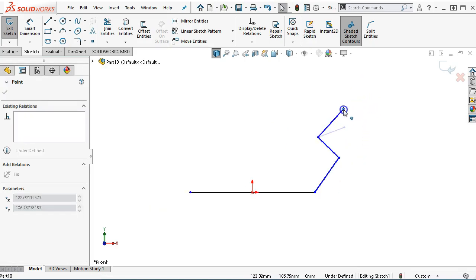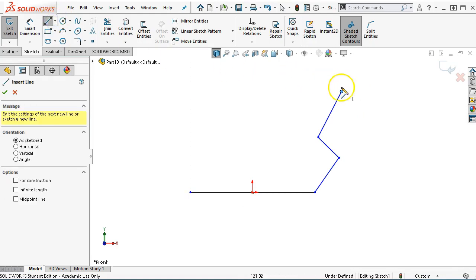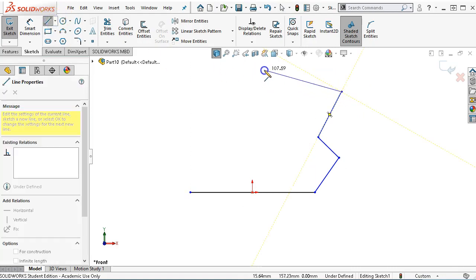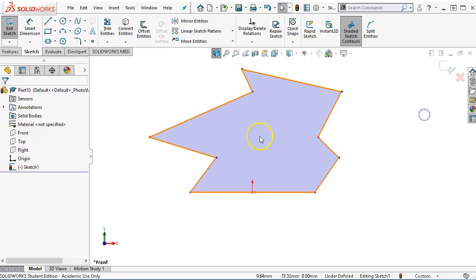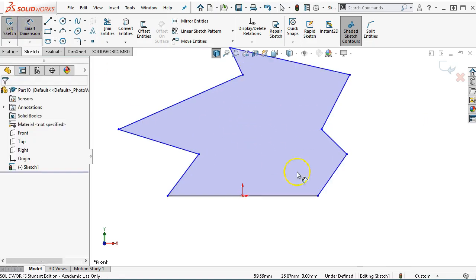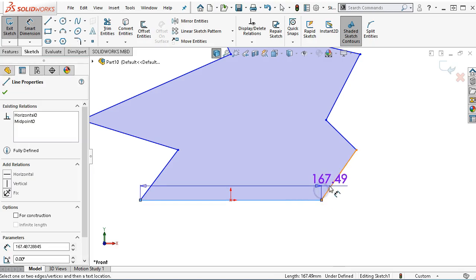Sometimes it seems like that would be about as easy just to go ahead and delete it and put it back in, but knowing how to correct some of these, there are times where we want to preserve geometry, so being able to make those adjustments is handy. I'm going to sketch this one all the way around, looking for those relations. A disadvantage of going all the way around is that it's a little more complicated, but I'm in that mindset to look for those relations as I'm dragging and dropping the lines, so that is the plus.